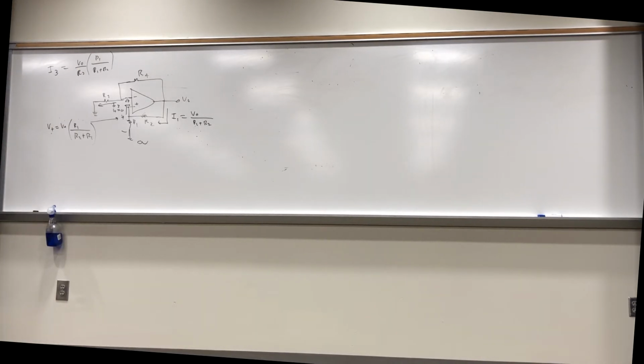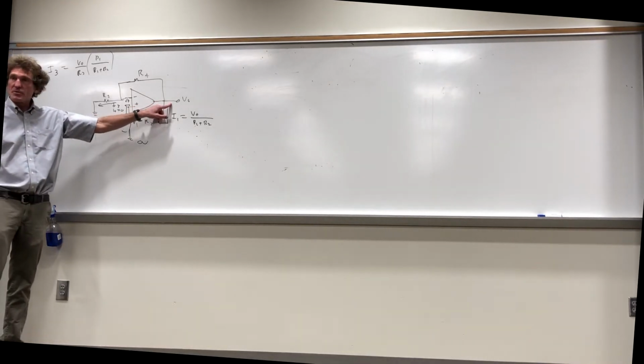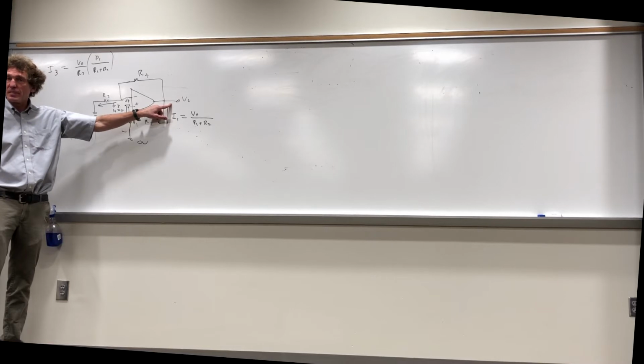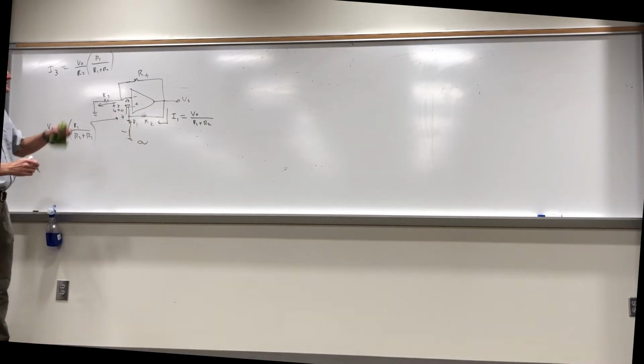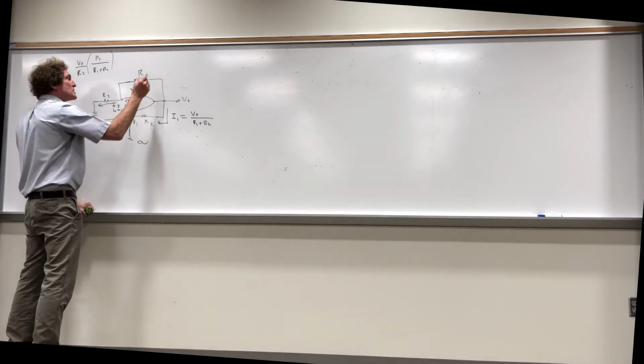How many see this? Right? We're just using the fundamental laws. No voltage across the inputs, no current input. We have a starting point. My starting point was the output voltage. You don't usually start there, but in some cases you do. Now I come here, and if I know that's the voltage there, what's the voltage here?